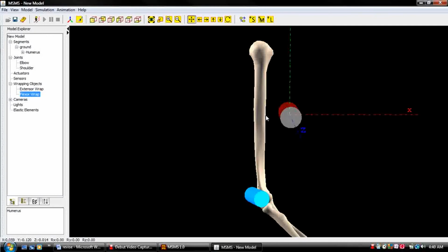And now to rotate it, we're going to click the Shift and Alt and X button and we're going to rotate it to 356 degrees about the x-axis. Whoops, I rotated too much. Keep rotating it.